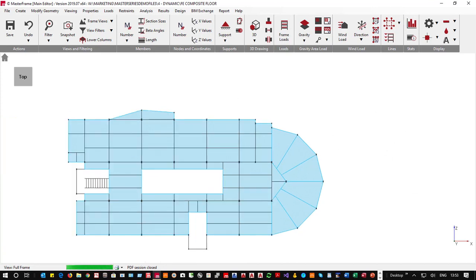Again, somebody's asking why we didn't pin them, we fixed them. Well, during your composite design for your ultimate state, they are pinned. But in these serviceability states for vibration, the stresses are actually quite low, and it's just feeling vibrations and things like that. You wouldn't think that somebody walking down a corridor would be putting any real stress on the whole structure.